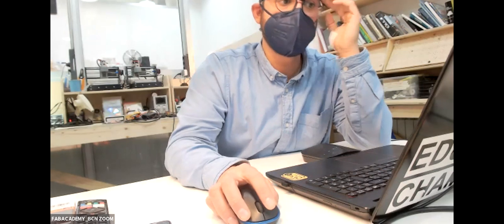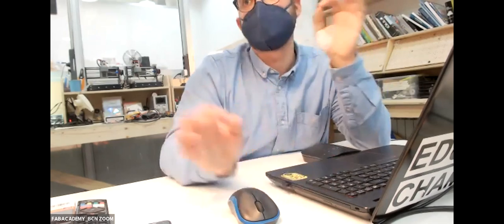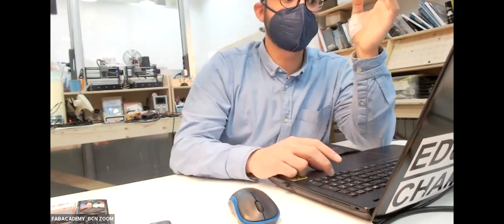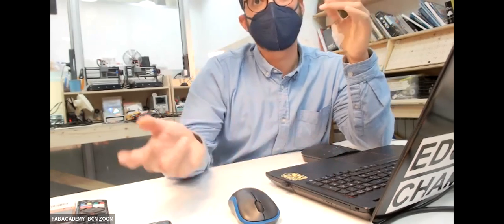So for example, this is putting a water bucket on top of the machine. So basically you're cutting inside water, so the dust stays in the water. This is a way to cut carbon fiber more or less safely. But here you cannot use an up cutter, because it pushes up and will splash everything. You need to use a down cutter.